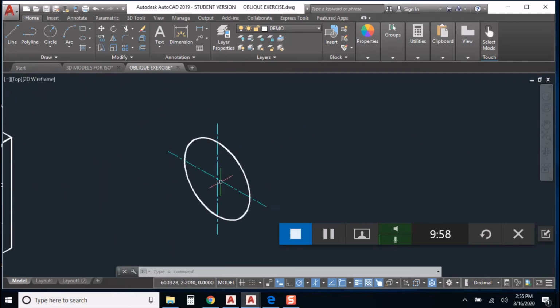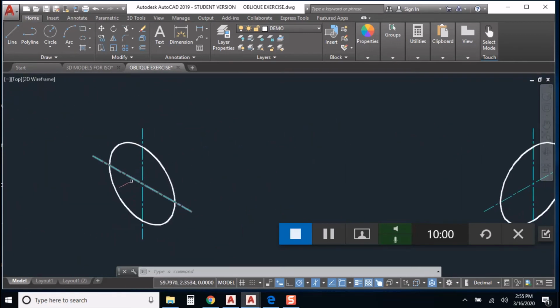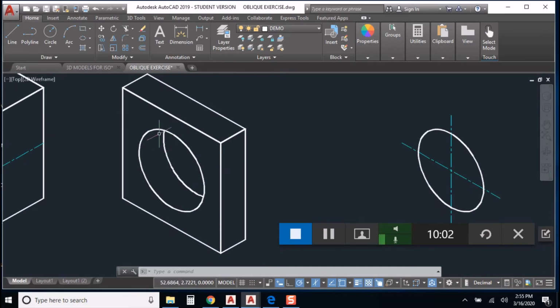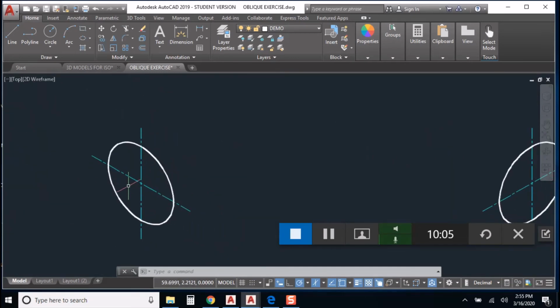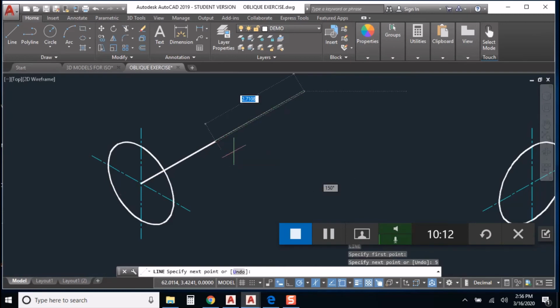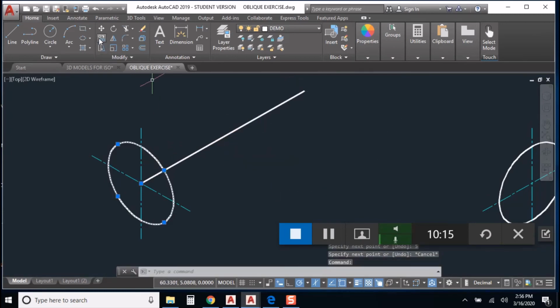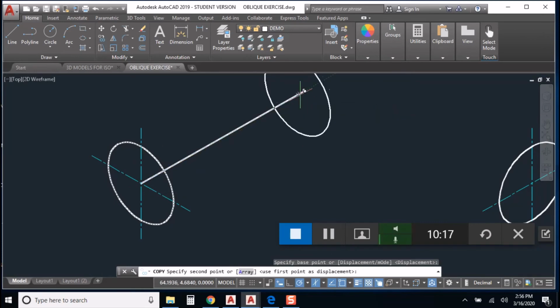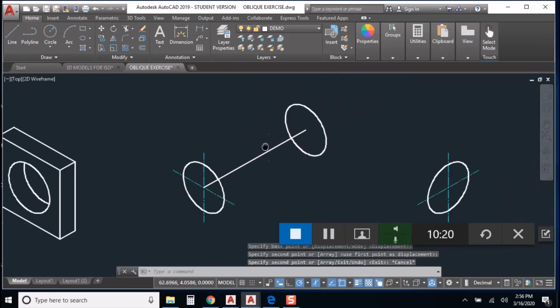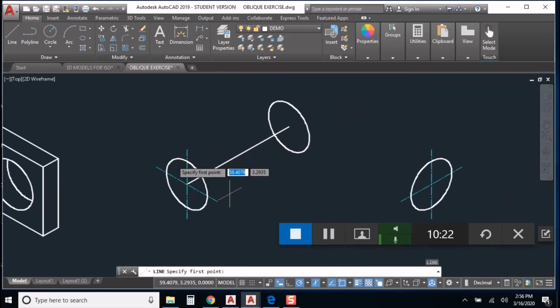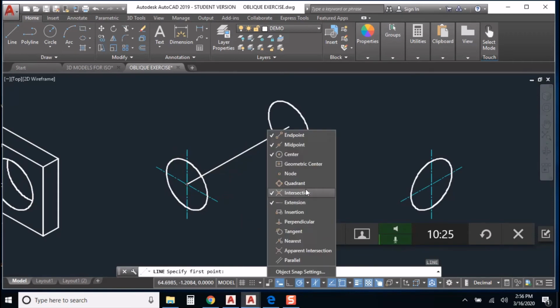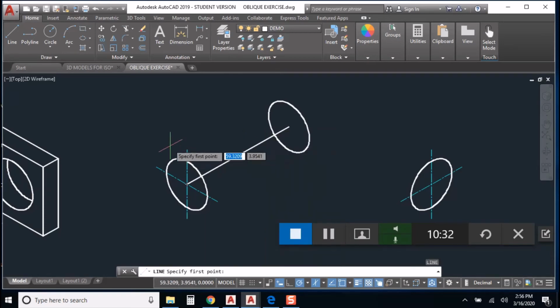If I was going to make something that was a solid cylinder instead of a cutout cylinder, because the hole is like a cutout cylinder, a negative cylinder, if I wanted to make a positive cylinder, we'll set our polar for 30. We'll go back as far as we need to go back, however many inches. I made that 5 inches back. I'll copy from the front to the back. And I'll draw some line work. Let's see, maybe setting up our tangent snap and turning off some of these other ones that are just going to get in the way. So line work,